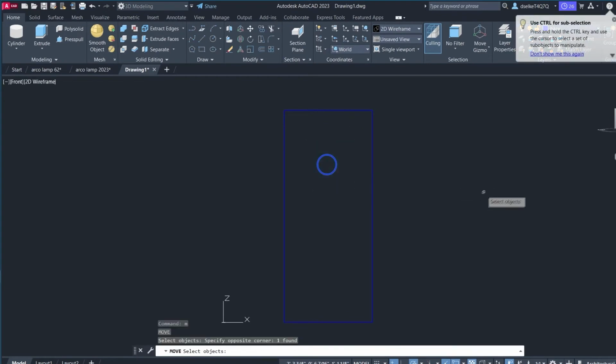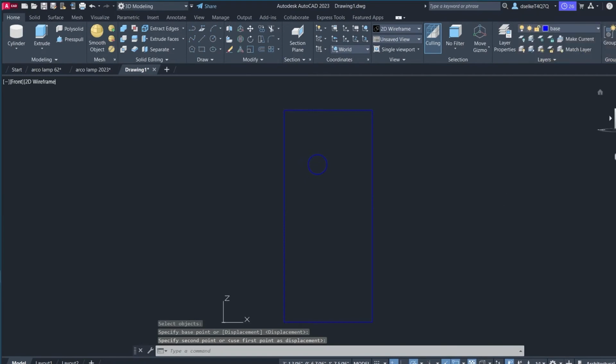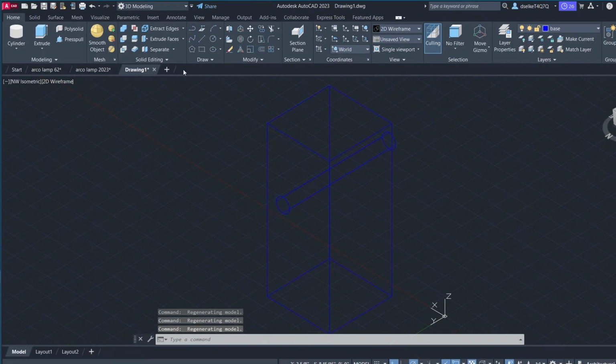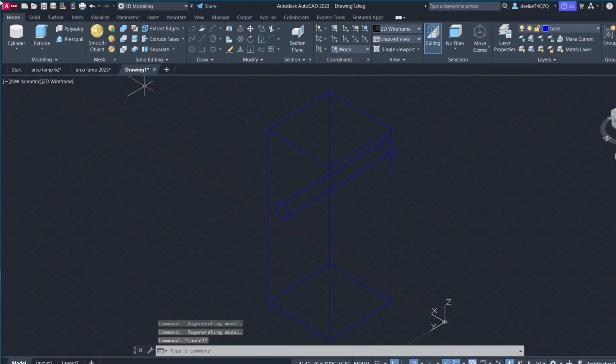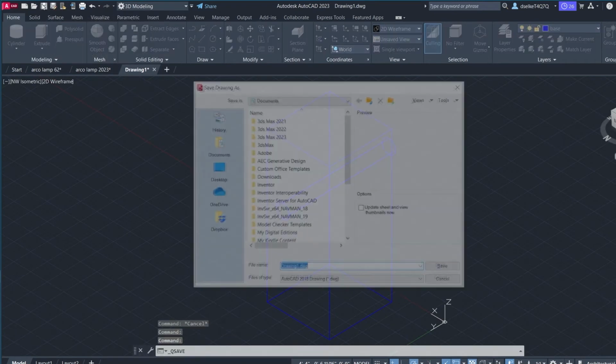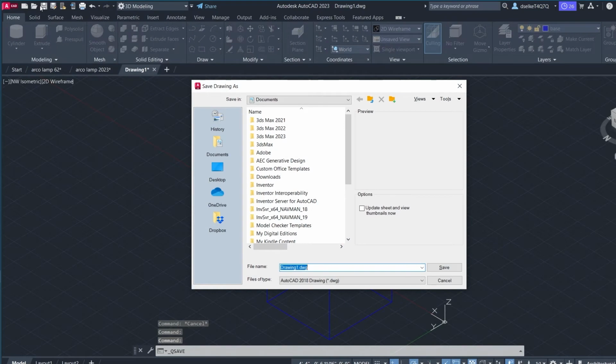So to lift it up, we can use the move command at relative. So we do at 0, comma 0, comma 8 inches, moving it up 8 inches in this case. So that's approximately still in the middle. We'd still like to move that over a bit. It's a bit towards one side. So that looks almost correct. It should probably be up a little bit taller, but that's going to be okay for this real quick demonstration. If you're going to use this model, it's going to be a really neat little thing. And we're going to do a quick rendering with light fixtures at the end.